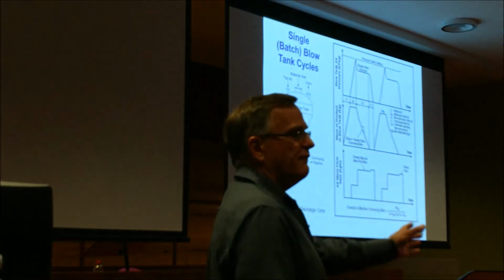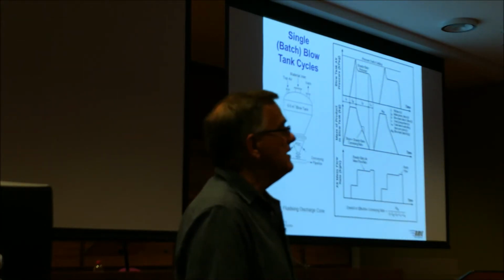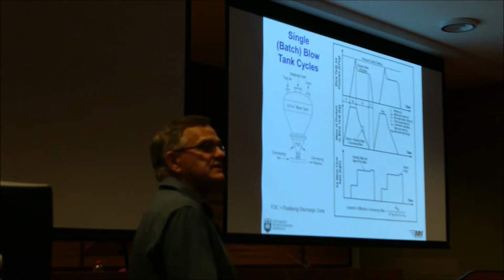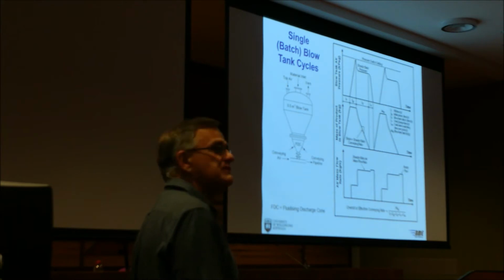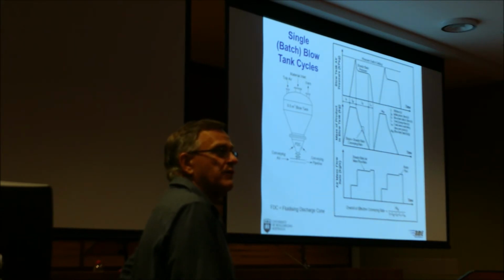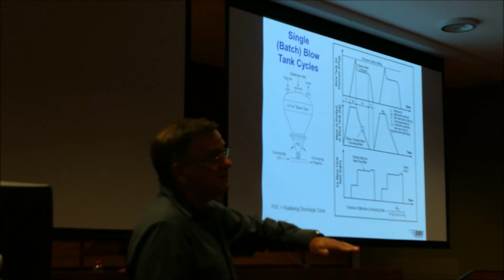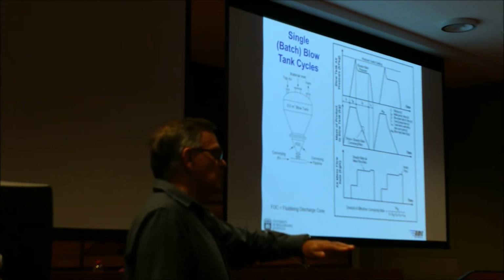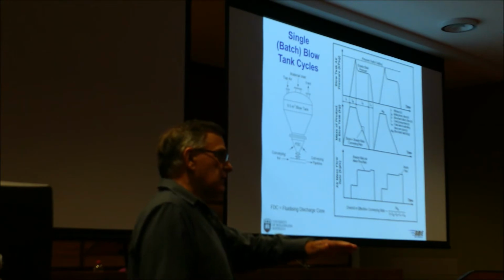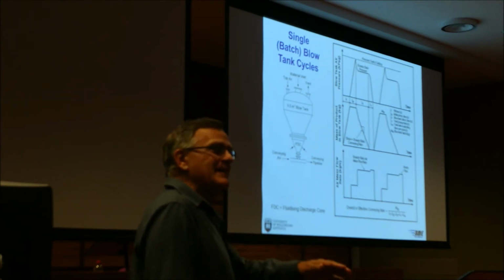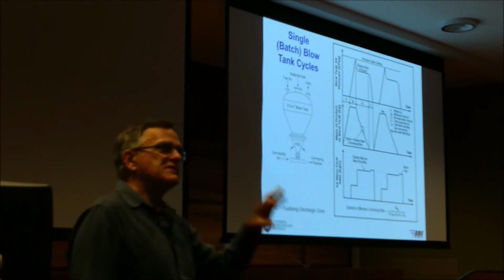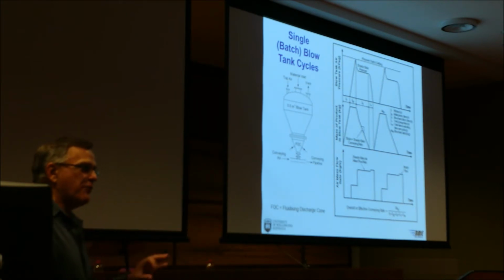You can add 5 seconds here, 4 seconds there, or whatever. I just put the whole thing together, 20 seconds. Most valves you can operate per cycle like that. But some people put a butterfly in there, and sometimes they don't put an actuator big enough, and when you open the valve, it can take a minute. And then you're waiting. So make sure you select your valves appropriately.